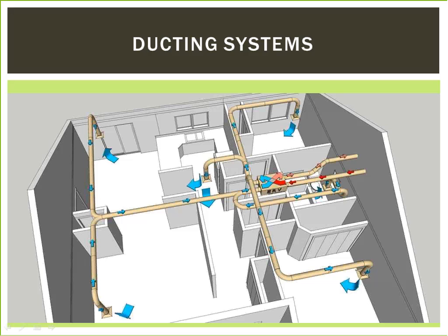Flexible ducts, known as flex, have a variety of configurations, but for HVAC applications, they are typically flexible plastic over a metal wire coil to make round, flexible duct. In the United States, the insulation is usually glass wool. A protective layer surrounds the insulation and is usually composed of polyethylene or metallized PET. Flexible duct is very convenient for attaching supply air outlets to the rigid ductwork. However, the pressure loss through flex is higher than for most other types of ducts.